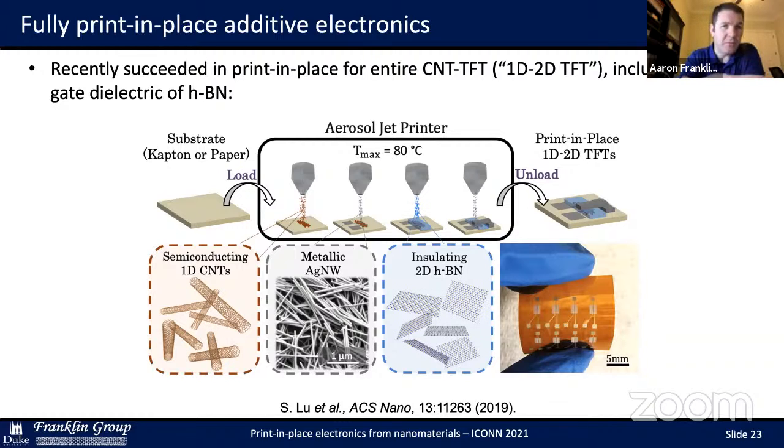And following the printing of all of those layers on, in this case, a polyimide or Kapton substrate, we immediately were able to test the devices. So we loaded that substrate in, printed all of the layers for the transistor, and then tested them immediately afterwards.